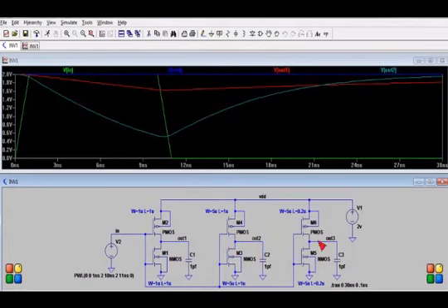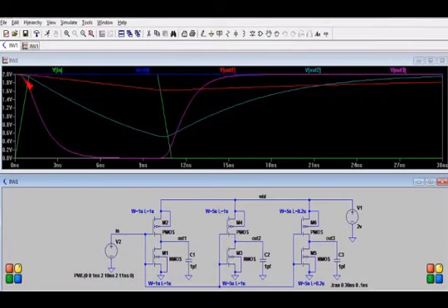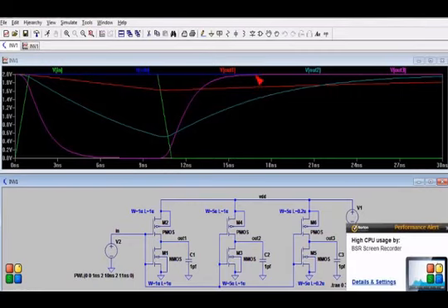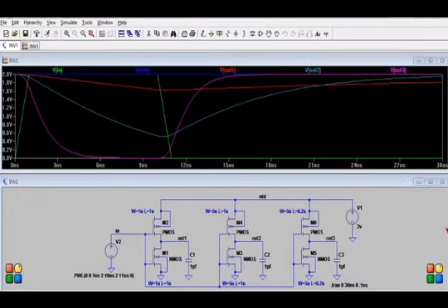So let's look at our third inverter output, where we have reduced the channel length from 1 micron to 0.2 microns, and it's still at the wide width of 5 microns. So here we see a very decent inverter response. We have the input rising up and the output being inverted to a logic 0 and becoming a very solid logic 0 at this time. When my input goes from a 1 to a 0, the output goes from a 0 to a very solid 1 at this point.